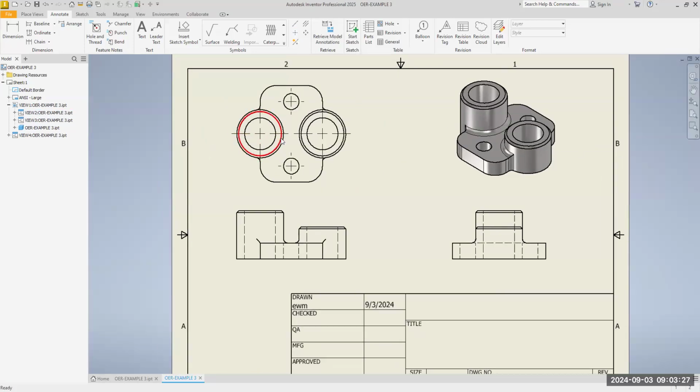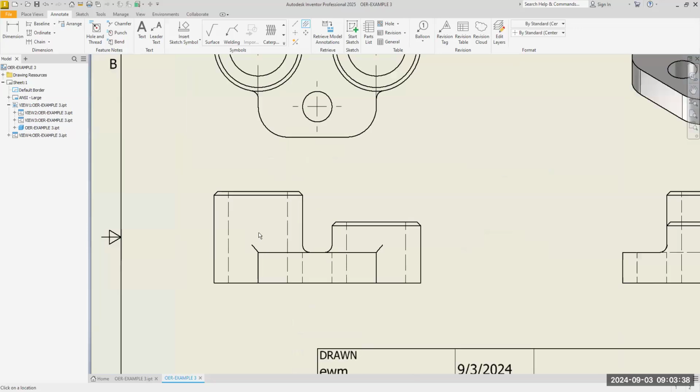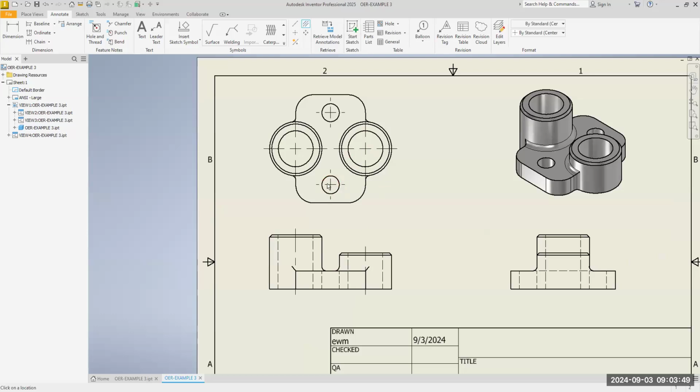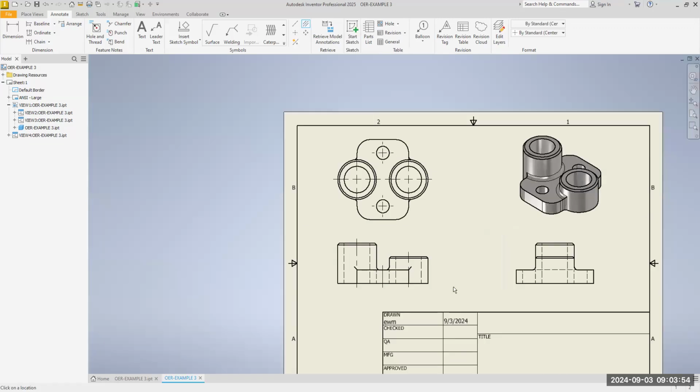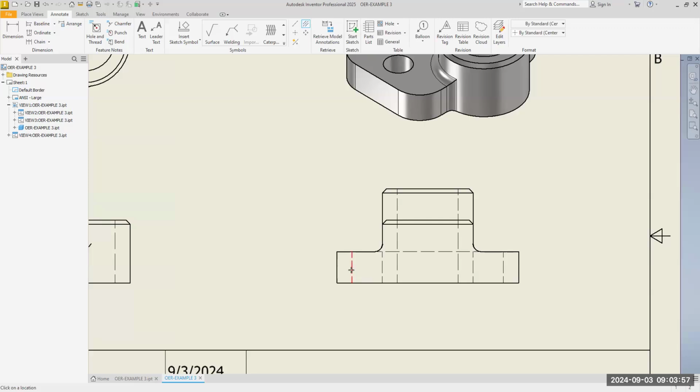These are center marks. Now I want to put the center lines. These are bisector center lines. So I go here and I click on this center line. Now watch very carefully. Click here, click here. That shows you the center line of the hole. Click here, click here. That shows you the center line of this hole. Now we can't forget about these two. Click here, and you can come over here. Same thing over here. Click, click, click, click, click, click, right click, cancel. All right.